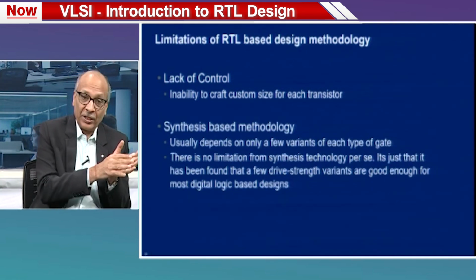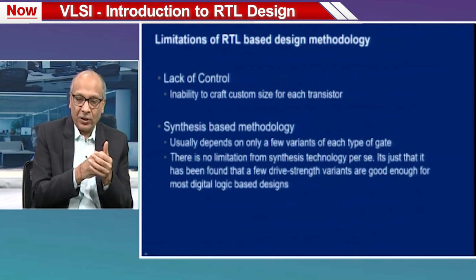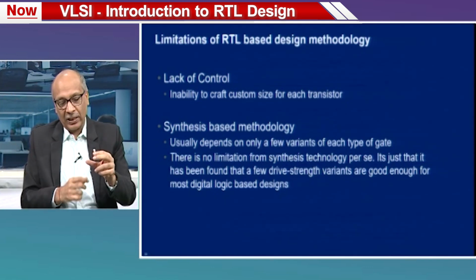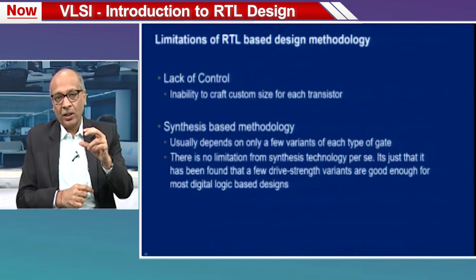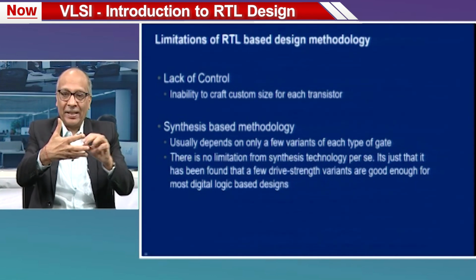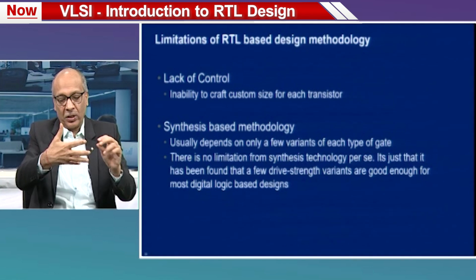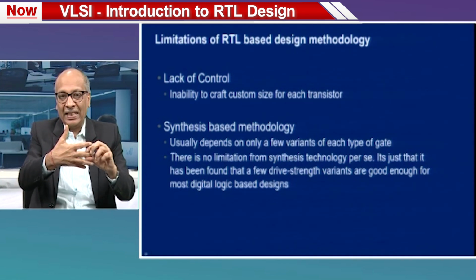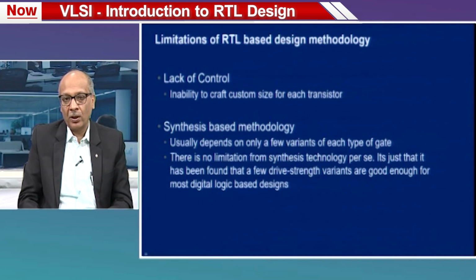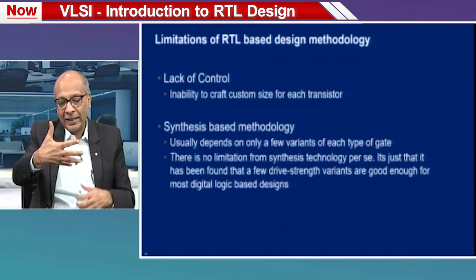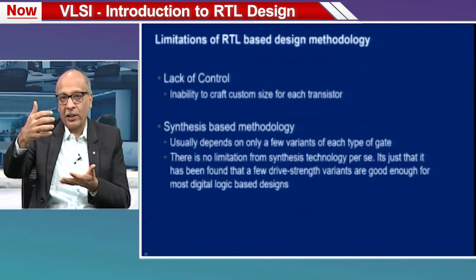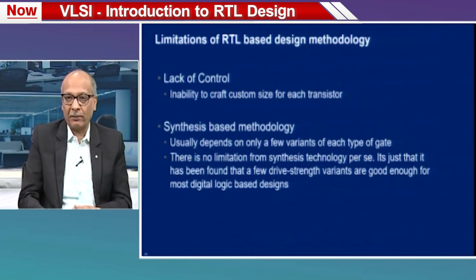We depend on synthesis. Since we depend on synthesis, you had seen it was making use of an ASIC library. In an ASIC library, what will happen is, for example, an AND gate, right. We will have 3 or 4 variants of the AND gate with different drive strengths, okay. So, the synthesis tool will pick one of these depending on what best suits the optimization requirements. So, effectively the AND gate drive strength, which could theoretically be a continuous variable, is effectively becoming a discrete variable also, okay.